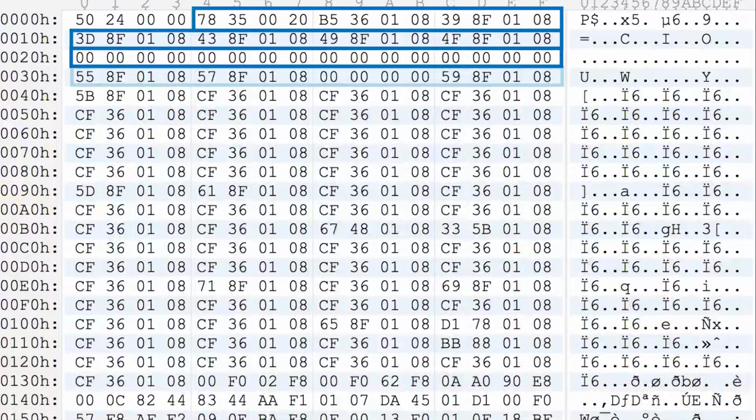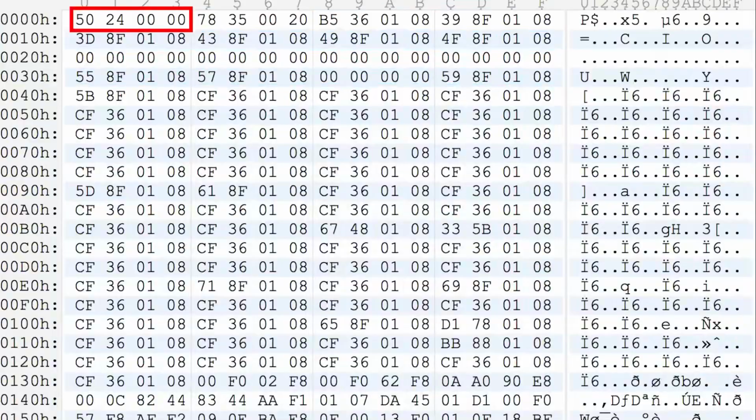And so luckily this particular device has its firmware in an accessible format because it takes firmware updates over USB. And if you look at the file that they upload onto this device, it has what looks very clearly like an ARM Cortex-M vector table at the beginning, but that's not the only thing in this file. There's also some metadata in the beginning and scattered throughout this file, and unless you want to sit there guessing at what the metadata means, like what kind of checksum is this, what kind of CRC could this be, is this a length that describes how much firmware there is before there's another blob, you're not even able to upload new firmware to the bootloader.